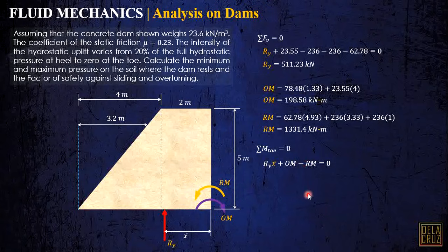If we rearrange this one, that is the formula. This is the formula we will see. Or if you do not want to memorize the formula, then you should understand this one. So, substituting, we have these values here, and that is 2.22 meters. After this, we should locate the eccentricity. What is eccentricity? That is the offset distance of the reaction force or the resultant force. This.